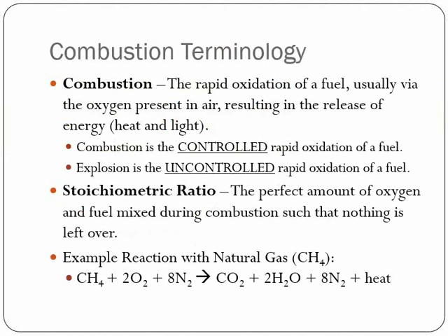There are also different ratio terms. Stoichiometric ratio is the perfect amount of oxygen and fuel that is theoretical. We're in the real world, so it's fairly rarely the case that this equation holds true. But from a combustion standpoint, we like to refer to stoichiometric as the baseline, and then when we set up our burners, we adjust them to be either with excess air or excess fuel, which I'll cover in the next slide.